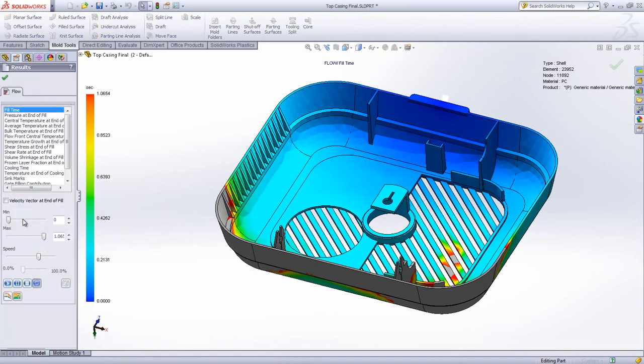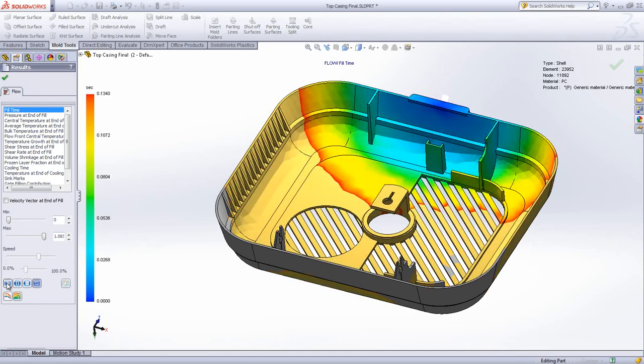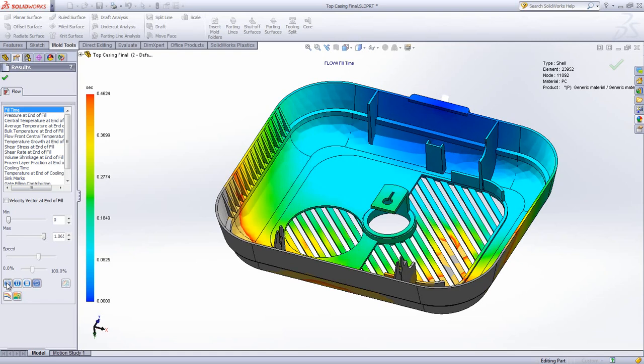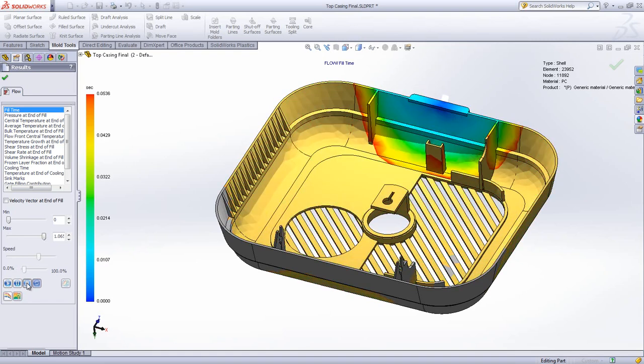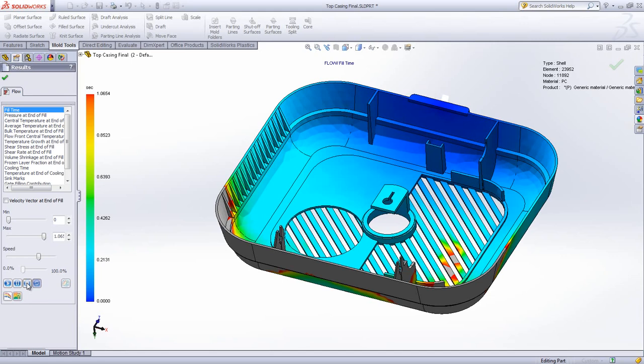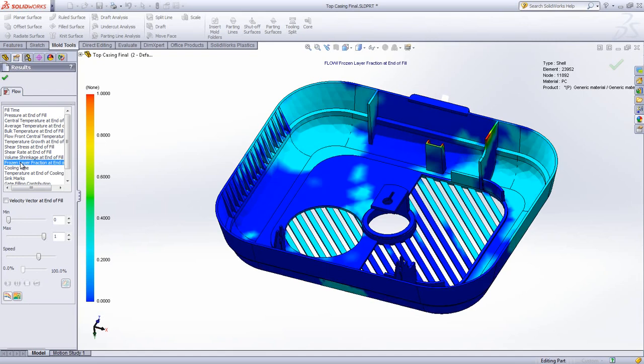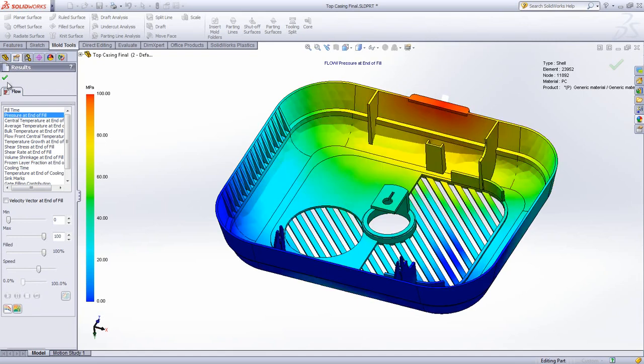With the same injection location and material, you can see that we ended up with another problem. Because we decreased the thickness too much, we created a short problem. No matter what you do, how you set up the machine, or how fast you inject the plastic, you just can't get the plastic to fill up 100% of the mold cavity. This moldy part would be nothing but defects.